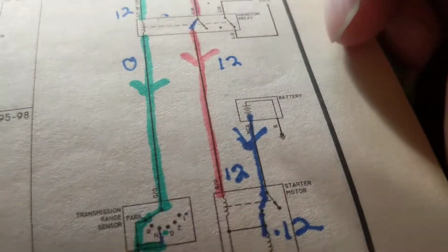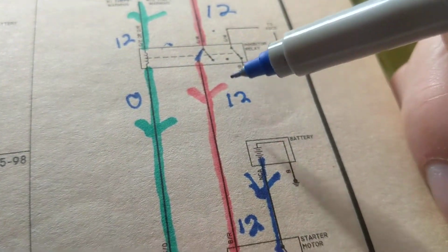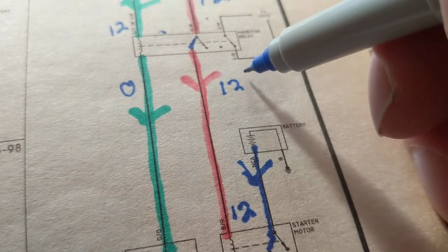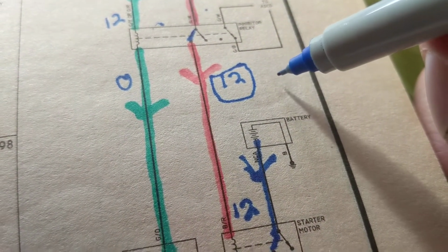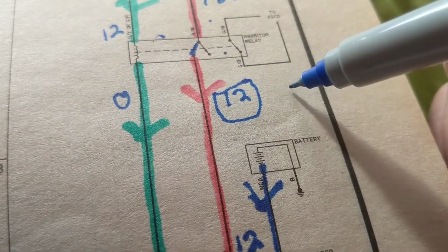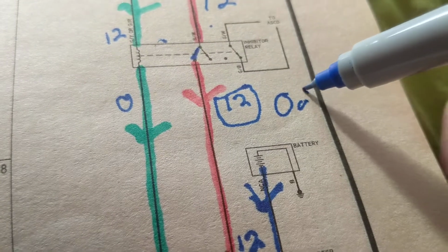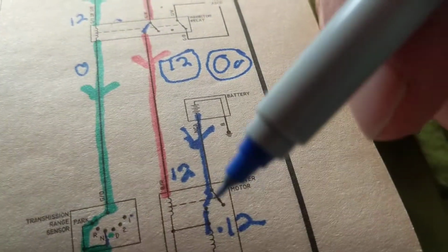Now, let's troubleshoot. Guess what? I come over here. I'm supposed to measure 12 volts. Correct? Guess what I'm measuring now? I went over here to this relay, came to this point. Uh-oh. 0 volts I measure. That's not good. That's not good, right? I cannot activate the starter.